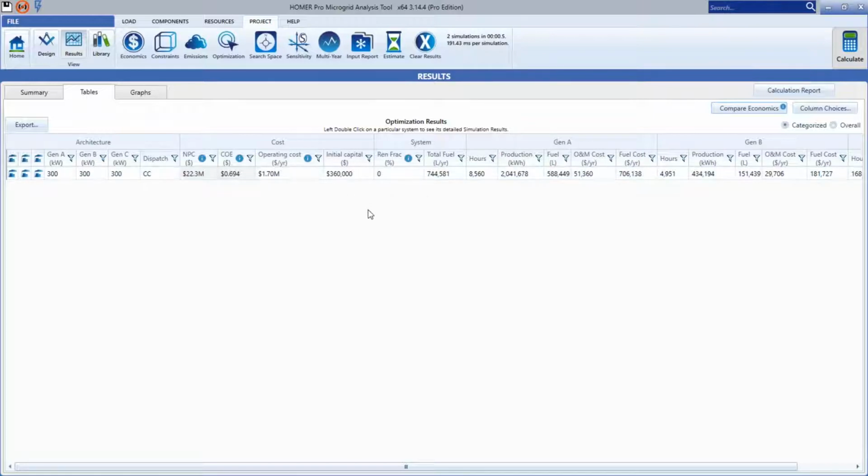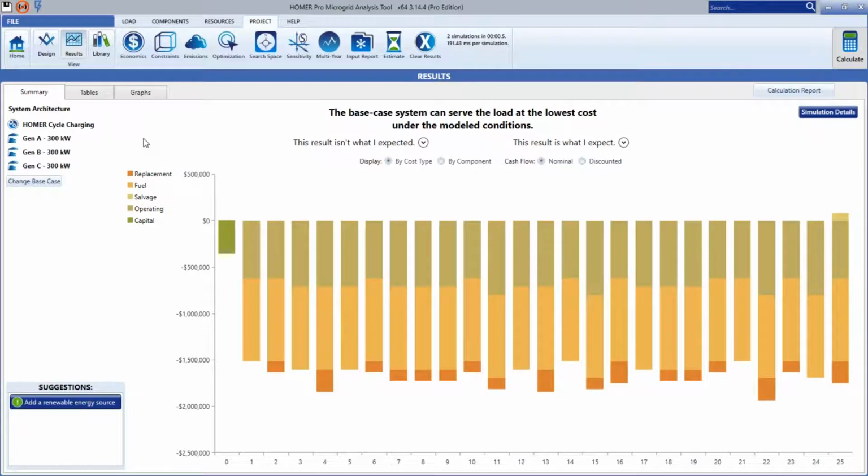If we consider the maintenance routine, this simply shows that the system cannot operate without a spare genset if we have to consider the maintenance requirements, especially the 500 and the 2000 hour maintenance requirement. Okay, so instead of just running on 2 gensets, there's usually a 3rd genset if you have to consider maintenance.